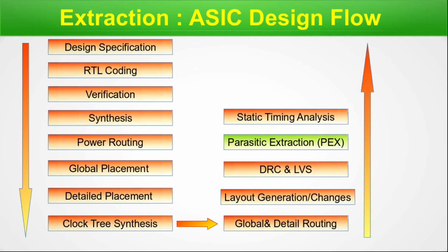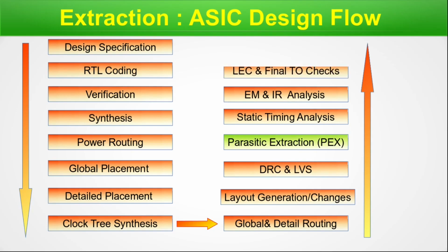Next, we have the static timing analysis, that is post-layout static timing analysis. Next, we go for the EM and IR verification or EM-IR analysis. Next, we do the ERC and final tape-out checks. And finally, the design is ready for tape-out. So folks, you have noticed that, let me bring my mouse pointer here.